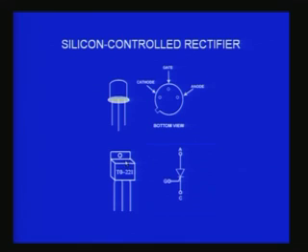They can withstand 5-6 amperes, and the corresponding circuit symbol is anode and cathode. You see there are 2 diodes, and then you have a gate. This is actually the figure of an SCR. In the case of an SCR, you will have only 1 diode and 1 gate. So the package is something very similar to this, and you would also see when I show a demonstration the actual device. Now let us understand how the silicon controlled rectifier works.